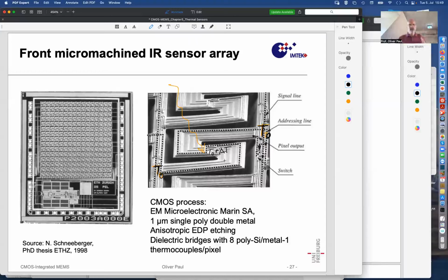That has taken a while, but after the under etching was completed, the remaining structure is then, of course, just this groove with walls made of silicon. And there are many such grooves here along this direction, separated by some ridges of silicon between the grooves on which lines can be supported and that are thermally well connected to the rest of the chip, so that the temperature T0 of the chip really is present here at these suspensions.